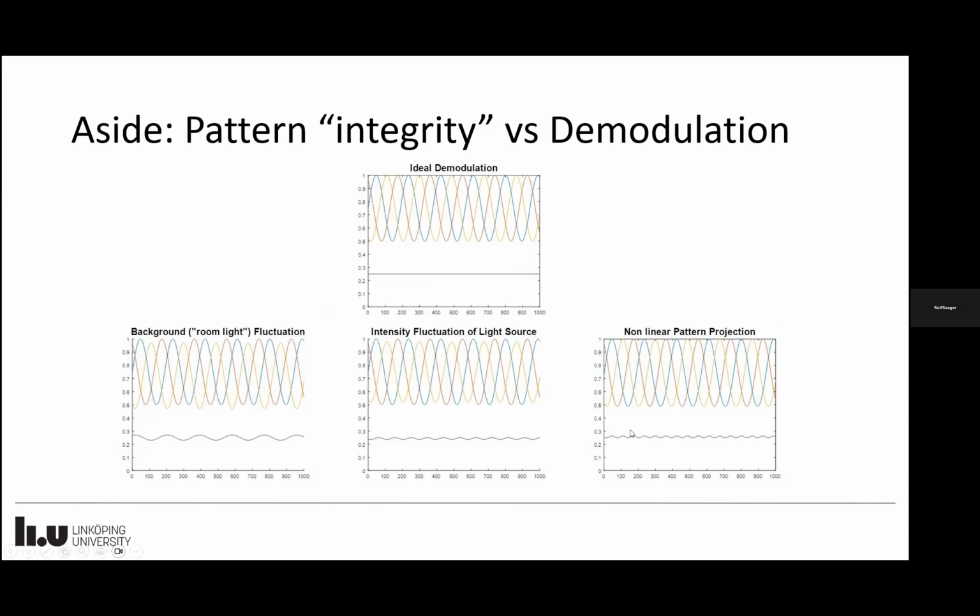But the nice thing is you can easily verify it, and look at any residual frequency patterns, and based on the period of the pattern versus the period of your frequency, you can see if it's this nonlinearity. It's usually a factor of 3 higher, or a factor of 2 if you have fluctuations in your light source.